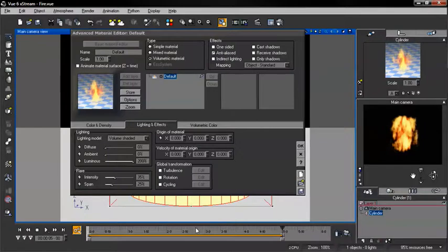And since we're currently not setting up any material keyframes where we're changing it over time, this will give us a nice 5-second animation where we can modify certain settings, and then if we render it, we have an active time frame. Because if we were just to leave this and set our material origin, and we went to render, we actually wouldn't have an animation. And that's just because we don't have anything defined. So we've set the position, since we're not really changing the position. If you are going to change the position, then you have a keyframe for it, and you can.